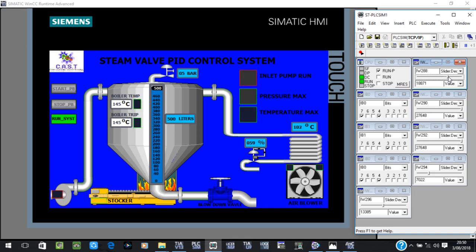So if I increase more, the faster it closes my temperature. If I increase to say 126, you see the valve closes quicker, and that will be dependent on my gain. But at the moment I'm at 101. Look at what happens at my percentage closing.